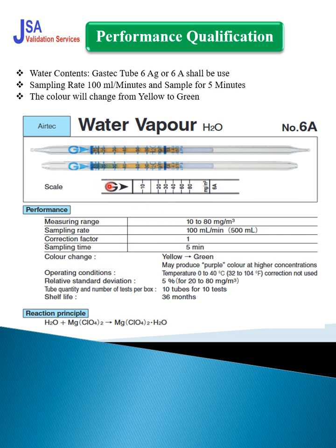Okay, so up to where the color has changed will be your reading. This is used in those types of generation or distribution systems where we are using a desiccant type of air dryer, silica gel, activated charcoal, which can reduce the dew point to minus 40 or minus 60 degrees Celsius. Then we can use this type of tube. There are fewer chances of water content, so for lesser traces of water vapor, we can use this type of tube.